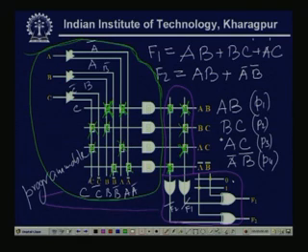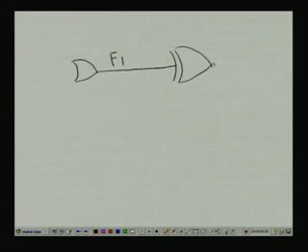What we have done in the OR plane, this is some extension or refinement of the PLA structure. We can add some XOR and the other input can be a 0 or 1. So, if we see that structure in detail, the output of this OR gate is F1, and that we feed to one of the inputs of my XOR.